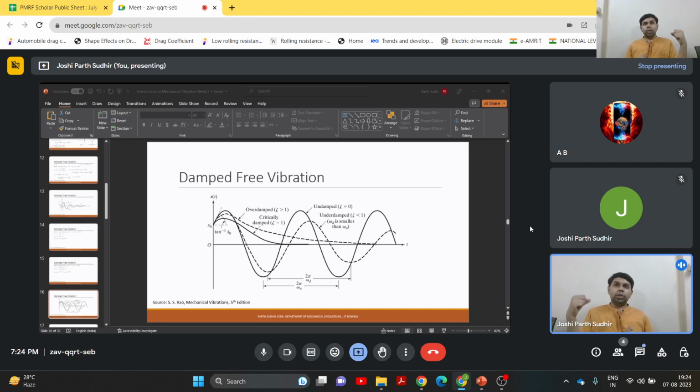When the piston pushes against the oil, the oil is forced to pass through those holes, and that creates resistance to the motion of the piston, which creates some kind of friction between the fluid and the piston. That is because of the viscous drag or viscous forces exerted by the oil on the piston. That creates the viscous damping.